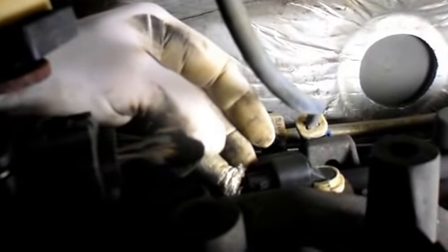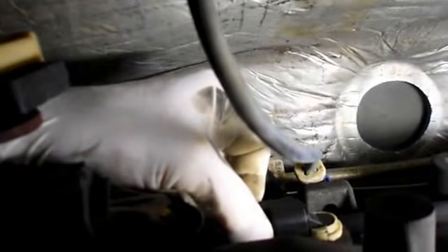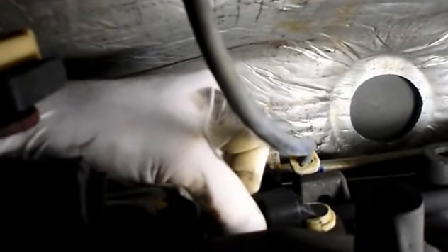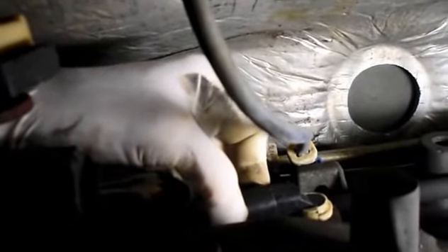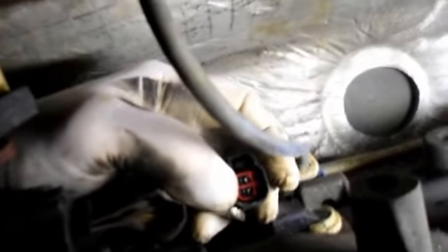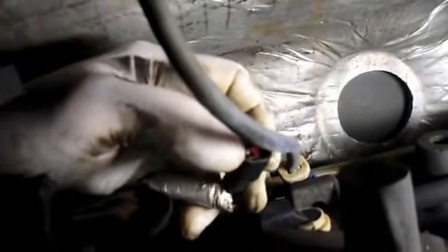So what you're going to do is get underneath here, and right on the bottom there's a plug. You pull down on this lock tab, you'll hear it click, you rock it, and you pull it off. Quite common is that if you look at these electrical contacts in here, you'll see a lot of corrosion on them. It's going to be hard to see anything in there because of the position it's in. Check your harness to make sure there's no damage. In this case, the harness looks like it's in pretty decent condition. The harness does run around up to the front of the transmission and then up.